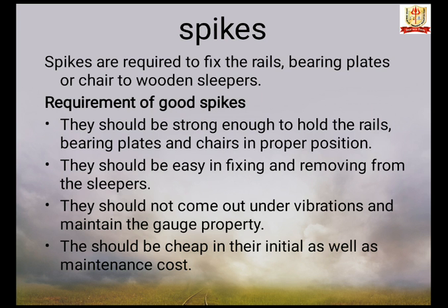Spikes. Spikes are required to fix the rails, bearing plates or chairs to a wooden sleeper. Requirements of good spikes: they should be strong enough to hold the rails, bearing plates and chairs in proper position. They should be easy in fixing and removing from the sleeper.